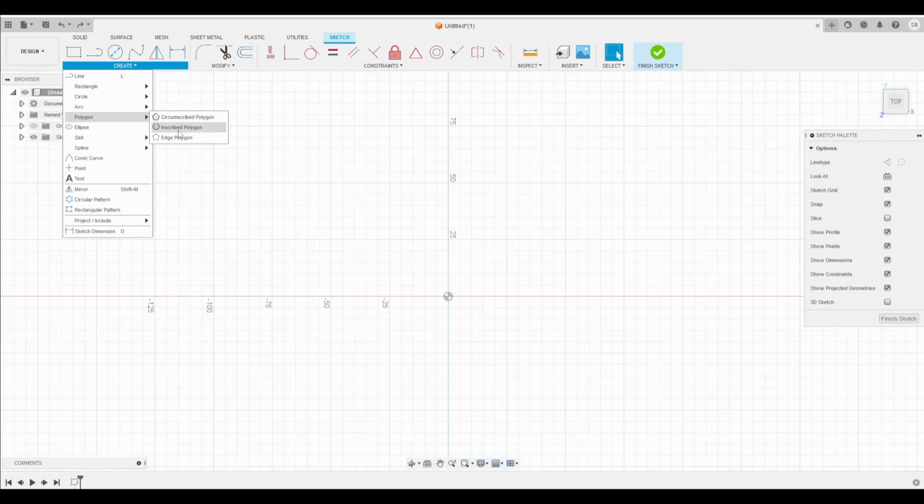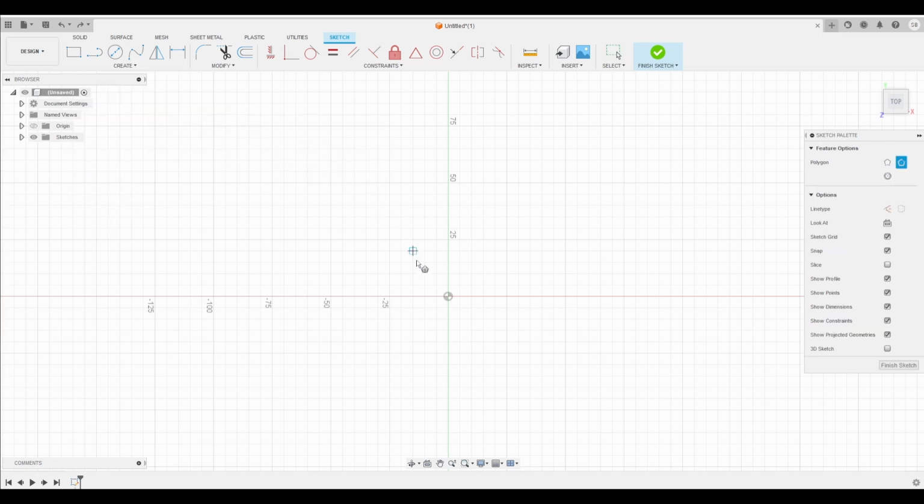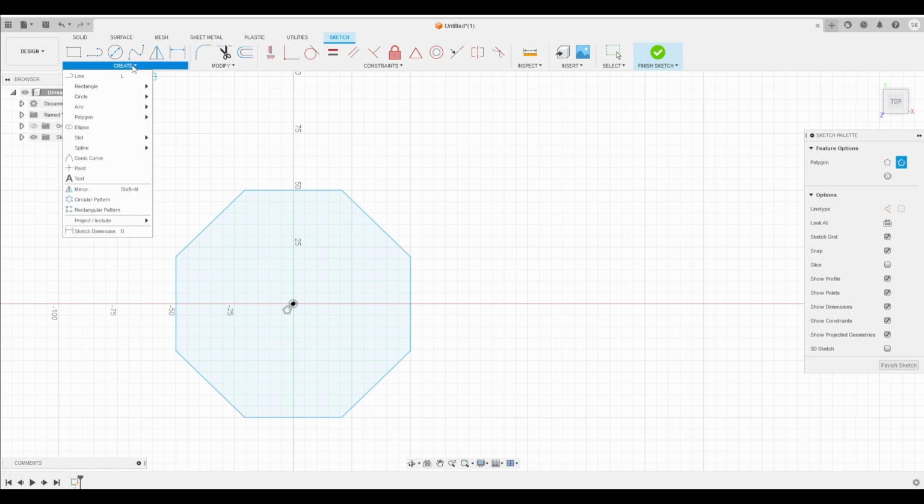and we'll continue off with the polygons. We have 3 types of polygon. Firstly, circumscribed polygon. This one has a circle inside of it that touches every edge at one point. You choose the radius of it to define the length, and you can also change how many edges it has by going here and changing the number. For example, 8. Now the polygon has 8 edges. Let's also define the radius of the circle and click it. Just like that, we have made our first polygon.